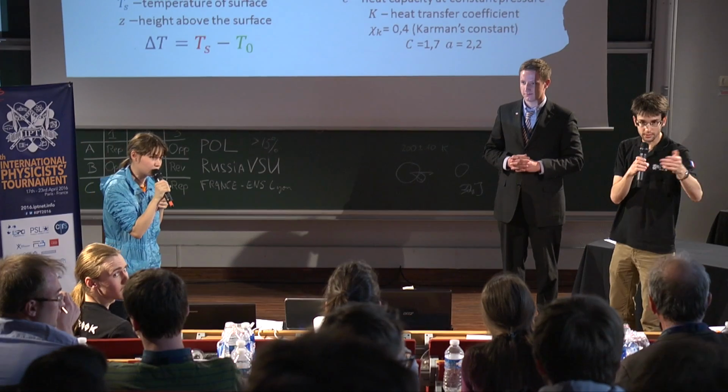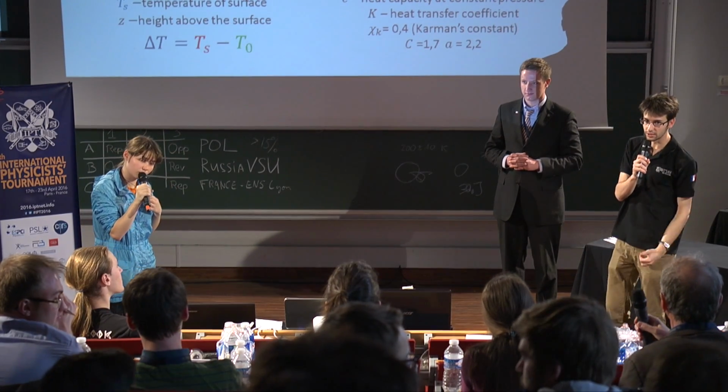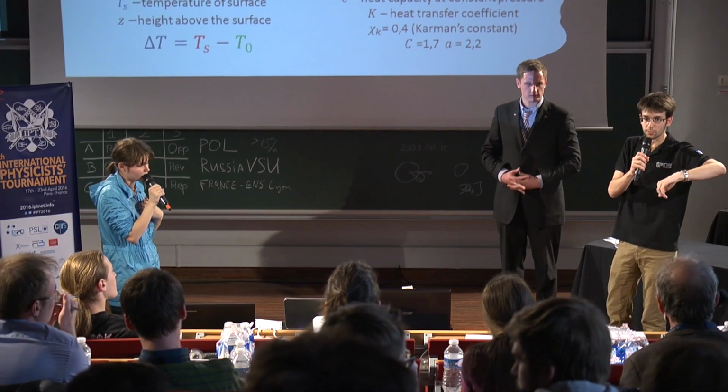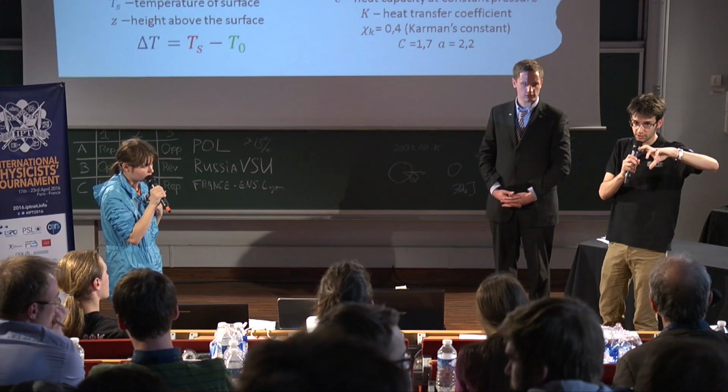May I? Actually, I think that the bigger the temperature of your plate is, the more complex the movements of the air are, and so locally you will have bigger density fluctuations of your air, so bigger variations of your optical index.